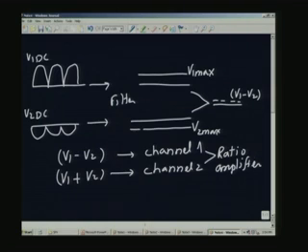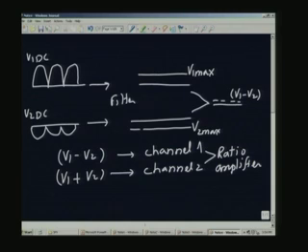So, this is basically what is going to be done in the case of LVDT transducer, which is connected to a pressure transducer. The pressure transducer is going to communicate the change in its or the displacement, which is due to the pressure difference. It is going to communicate to the core of the LVDT, and the core of the LVDT is going to create two AC voltages. These two AC voltages are demodulated to get two DC voltage outputs.